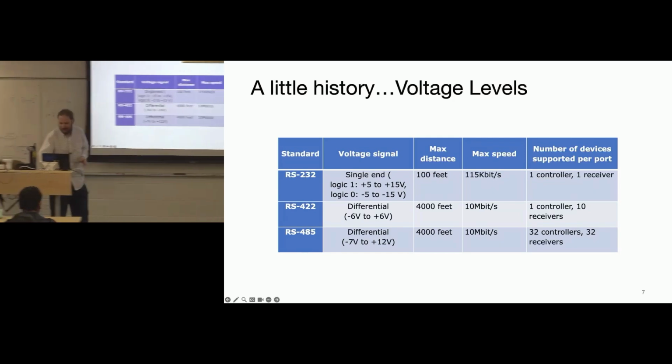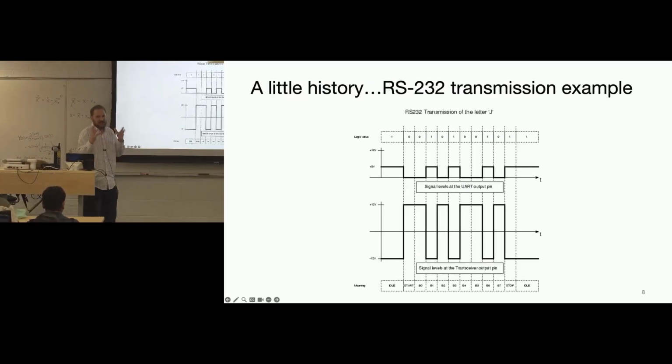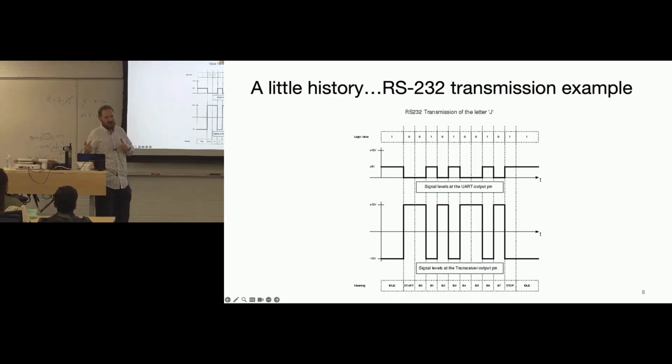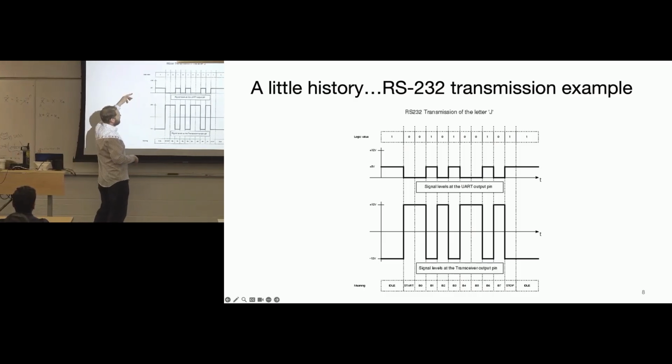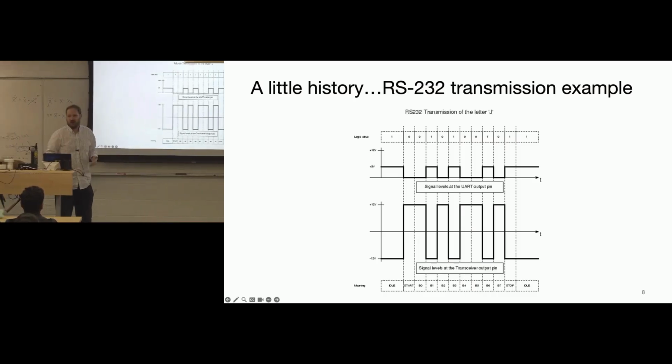Okay, so there's different. Now, when I was an undergrad like you, I was working in a research lab, and they said, okay, there's some old legacy piece of equipment and figure out how to get your microcontroller to talk to it. And I didn't know anything about anything, and I kept on struggling for a long time trying to figure out why my microcontroller is putting out positive highs and lows, and then what was coming out of the RS-232 converter was inverted. I couldn't figure out what was wrong with my protocol.